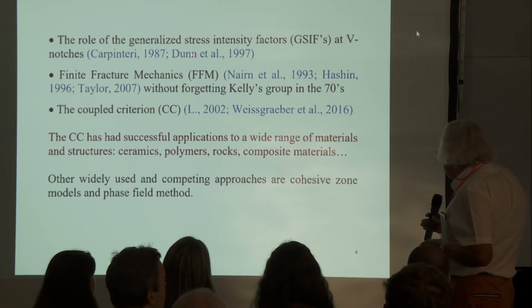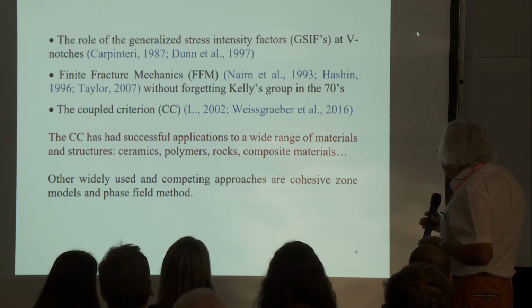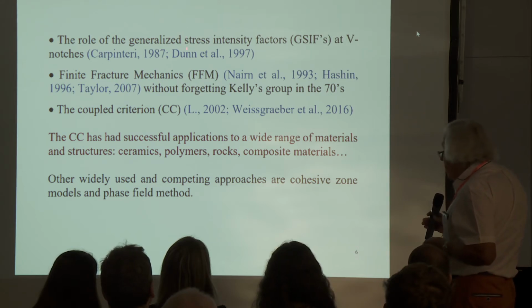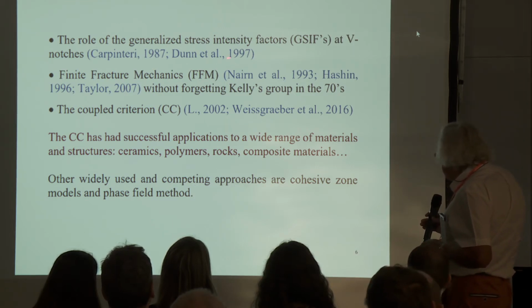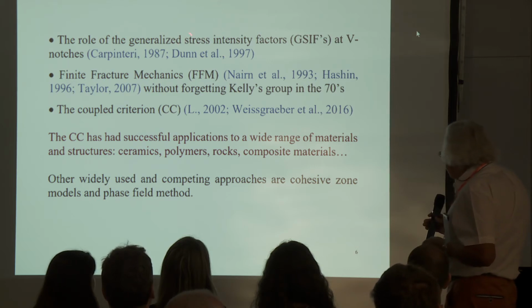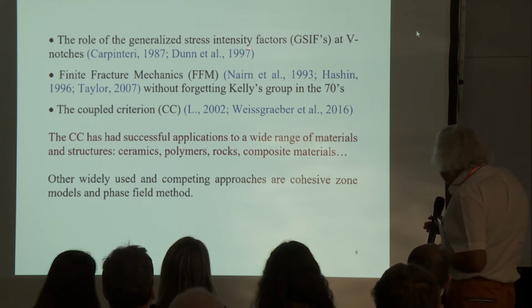It is an experimental work, but it is very important because they show that the generalized stress intensity factor is the right parameter to be used to predict crack initiation at a V-notch.